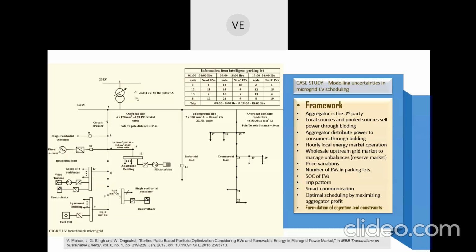For a PQ bus and PV bus, P is fixed, active power is fixed. For a PQ bus, reactive power is also fixed. For a PV bus, voltage is fixed. So if based on these forecasts you are executing the load flow, your power injections at each bus depend on your assignment of that particular bus, right? Your assignment in the sense PV, PQ or slack.